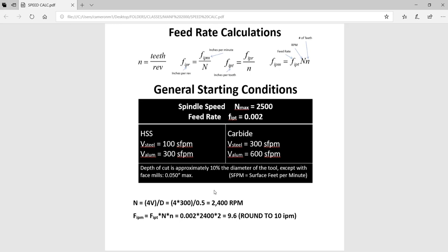When we start cutting in CAM, we're going to be using the full spindle speed, cutting as close to it as we can. This is going to give us a more efficient cut and a better surface finish, but more importantly, it's going to allow us to ramp up our feed rate, how fast the cutter is moving linearly through the part, because the time savings that we'll run into using a higher RPM are actually quite significant.